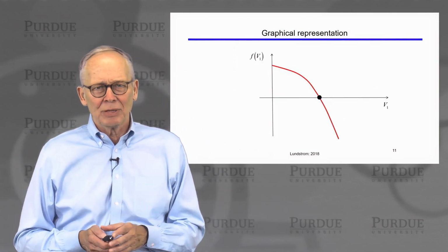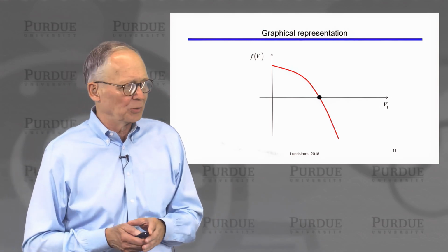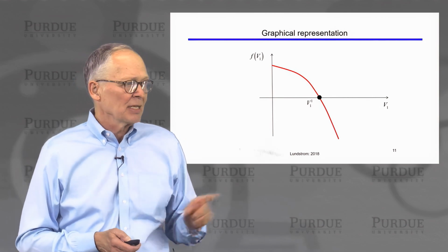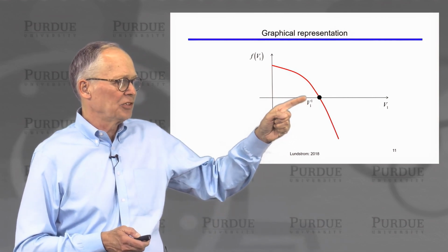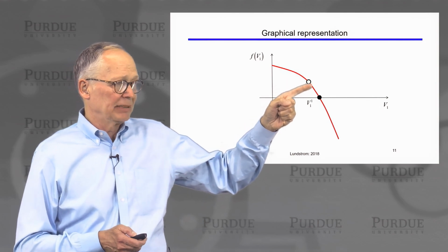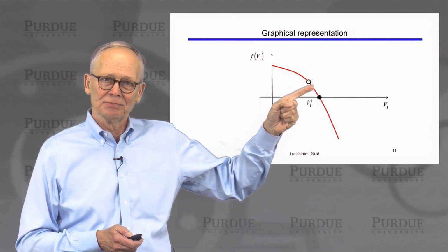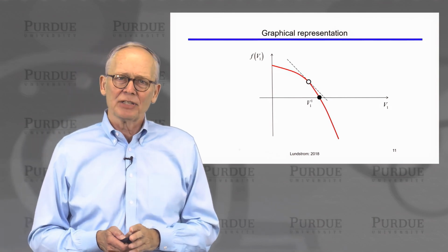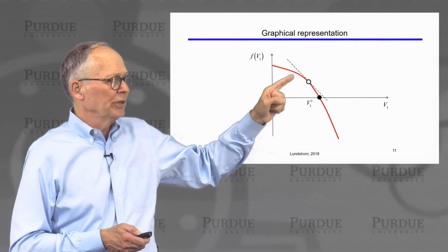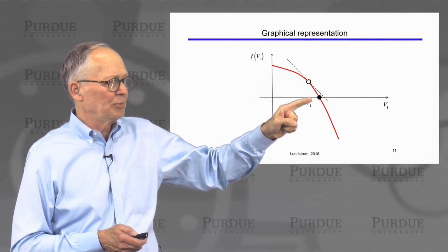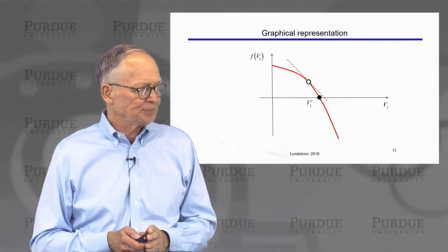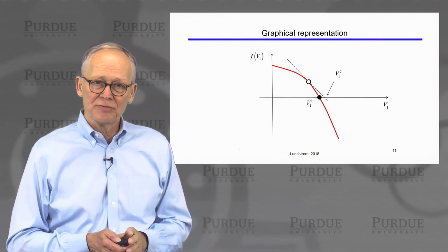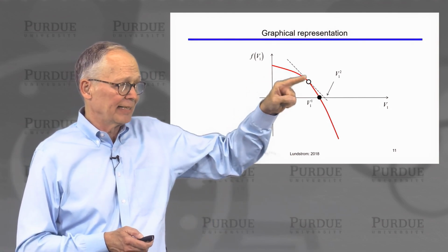So here is a graphical representation for how this Newton's method works. We have this nonlinear function. We're trying to find its solution. We make a guess as to what voltage satisfies that equation, but that voltage doesn't make the function 0. So we're up here. We're not at the solution. When we do the Taylor series expansion and only keep the first term, what we're doing is fitting a straight line to the function at that point, extrapolating to 0, and saying we now have a new guess. We're going to guess the voltage V1 second guess.